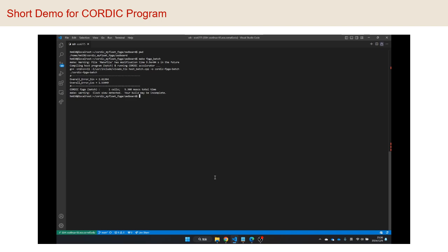These are the root mean square errors in percentage. So this result indicates the sine and cosine calculations got 2.6% and 1.5% error respectively, and it matched the expectation of using bfloat in the CORDIC algorithm that we've discussed before, and it used a time of around 5.3 milliseconds in total. So our templatized floating point is proven to successfully work on the FPGA.